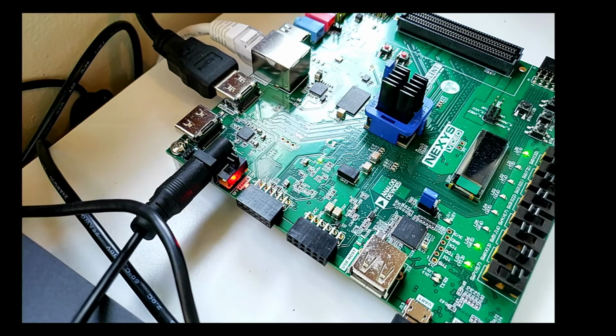and gives us a nice kind of binary counter type of design, right? Where in designing this, I would actually start with the adder as the first component here, and it'd be maybe just a +1 adder, and takes that value and actually just does an up counter. And there you would definitely want a reset line for this to work properly, and then connects that result to the LEDs. That'll give us a nice kind of little blinking pattern on our LEDs.